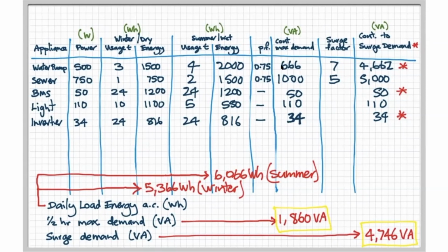In fact, even better than that, Mike, and I'm a big fan of VSD pumps for off-grid, is you can massively oversize your pump and hardly ever use that power. So I've got a 1900 watt Enviro something pump, because I can't remember its particular model name. It's a 1900 watt pump, but it actually runs at about 100 to 200 watts most of the time because that's all the demand the water needs. And so the VSD operates at very low power levels. So that means you're actually saving on wasting energy by circulating high bursts of power through your cables. Any other questions there?